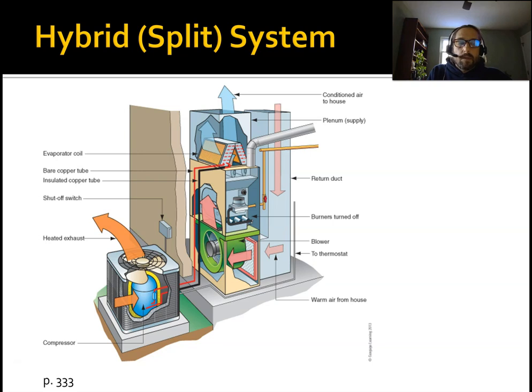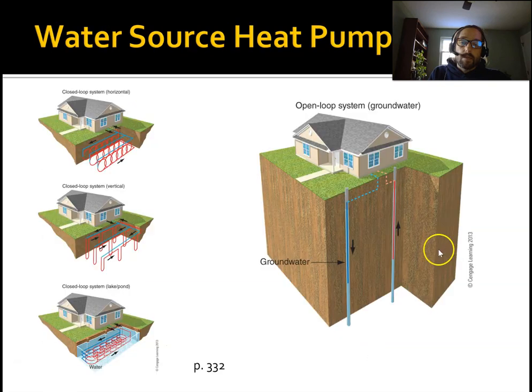Now, once it drops down a lot colder than that, then it may have trouble operating at an efficient level, and you can program it to automatically switch over to natural gas at specific outdoor air temperatures. So there's different ways to set up a split system. But again, these are pretty common if you have gas service in your area, because gas right now is relatively inexpensive. But at higher temperatures, if it's like 40 degrees outside, 50 degrees outside, you don't need to use the gas. You can use your heat pump, and it'll be cheaper to operate than gas.